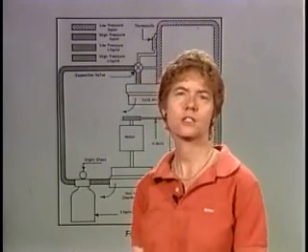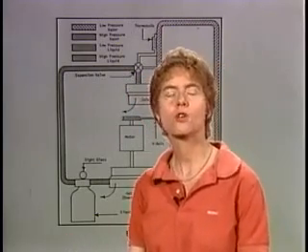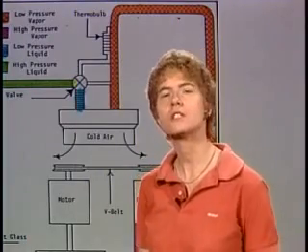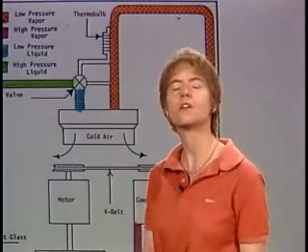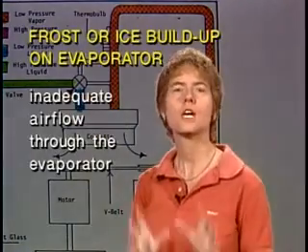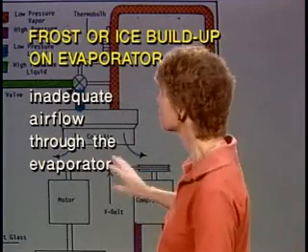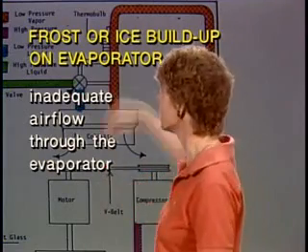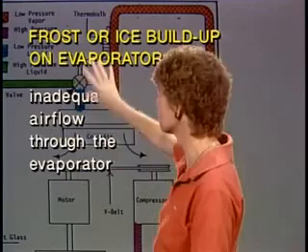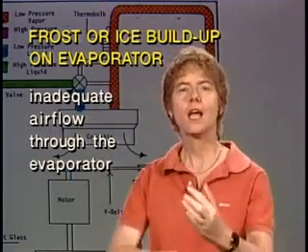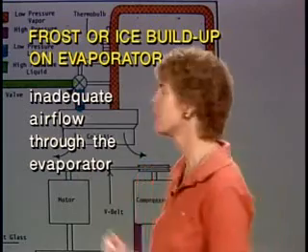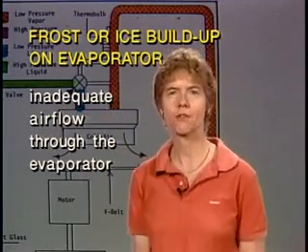Now, in this system, if you have frost or ice buildup on the vapor cycle cooling system evaporator, the probable cause is inadequate airflow through the evaporator. For some reason, you're not getting enough airflow through there to absorb the cold of the Freon, and that's letting frost or ice build up on the evaporator.